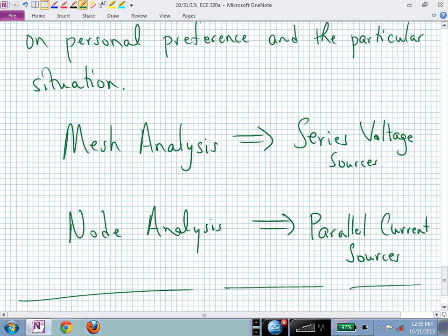Now it's a V sub C of S, and you need to find what that capacitor voltage is in the time domain. Oh, just look in my table, inverse Laplace transform, and you have your capacitor voltage as a function of time. And you now know how to incorporate all the different initial conditions. And you can obtain those initial conditions by looking at limiting behavior in your circuit before a switch gets thrown, for example.